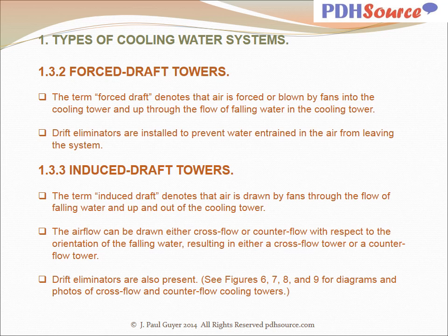The term forced draft denotes that air is forced or blown by fans into the cooling tower and up through the flow of falling water in the cooling tower. Drift eliminators are installed to prevent water entrained in the air from leaving the system.